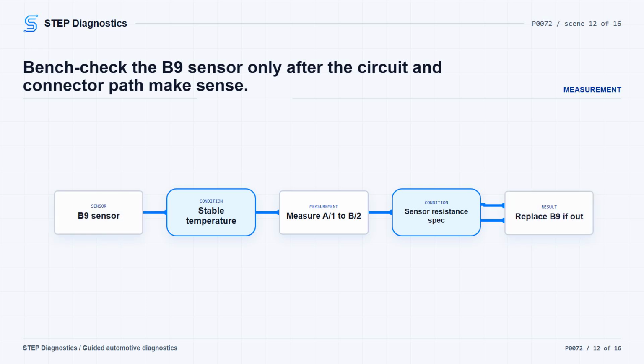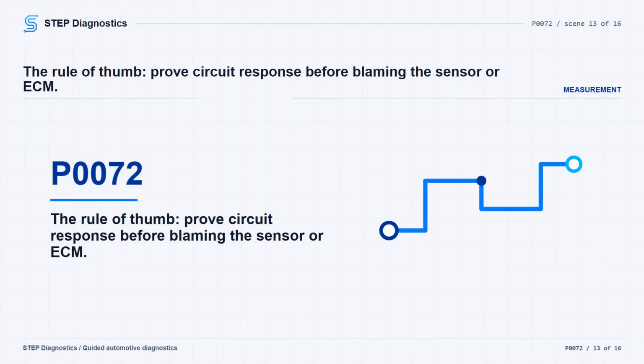Disconnect the K20 engine control module connector. Then turn the ignition on or put the vehicle in service mode. Test between the signal circuit at the component harness and ground. You want less than 1 volt. If it is 1 volt or greater, repair the short to voltage on the signal circuit.